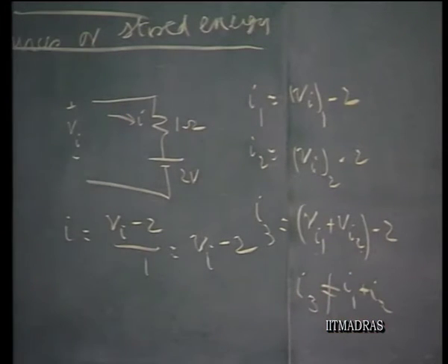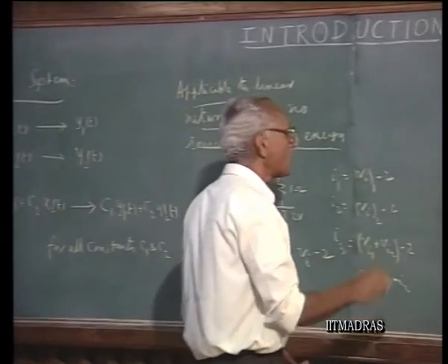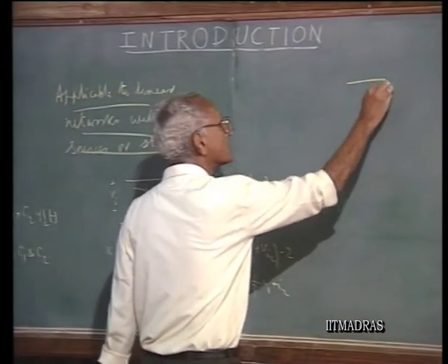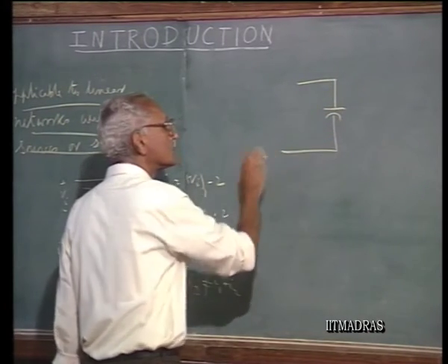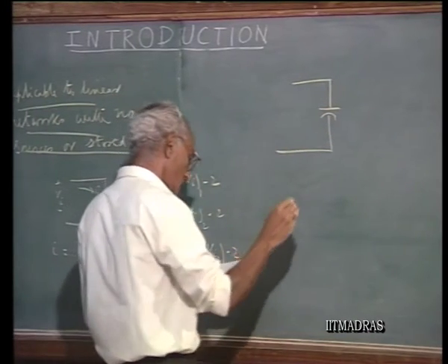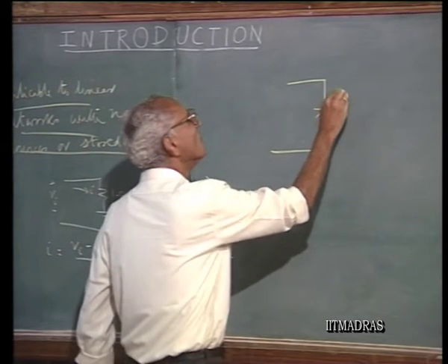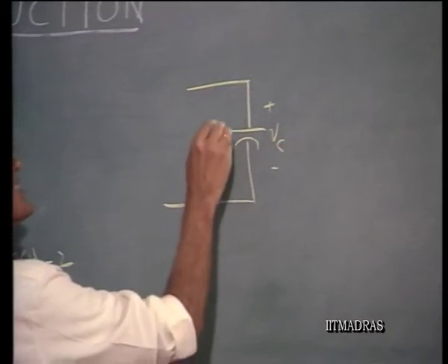So when you apply this linearity principle or superposition principle, you must make sure that you are applying it to a network which does not have sources or stored energy for that matter. Let us take a second example to illustrate the second point which I have in mind. Suppose I have a capacitor which has got an initial stored voltage Vc, this is C,